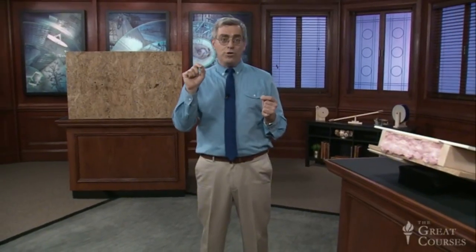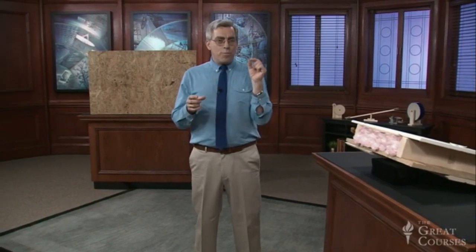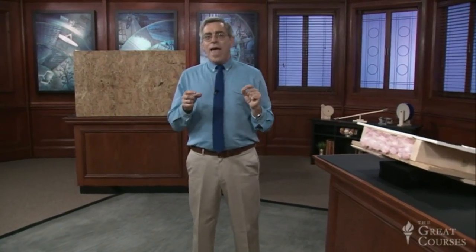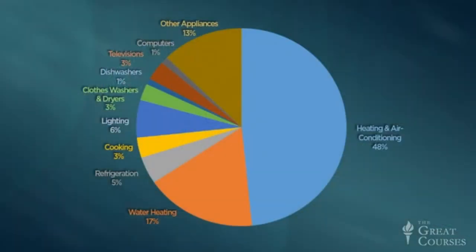Your HVAC professional can determine the required system capacity based on a calculation of the total heating and cooling loads for your house. But don't forget that the heating and cooling loads will be substantially reduced by improved insulation and sealing and by high-performance windows and doors. So it's essential that these enhancements to the building envelope be planned or implemented before the capacity of the HVAC system is determined. If not, you'll probably be buying more capacity than you really need.